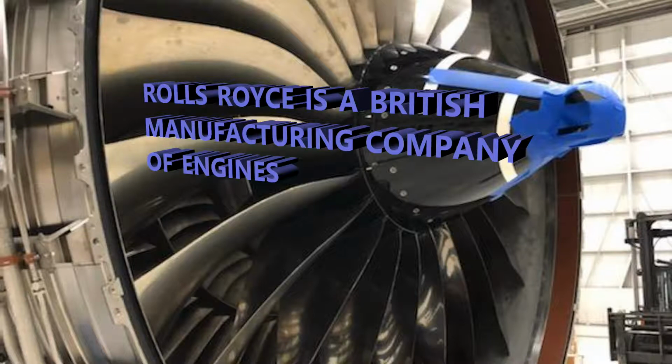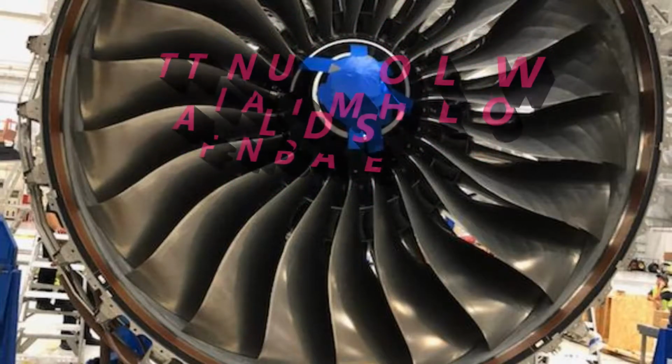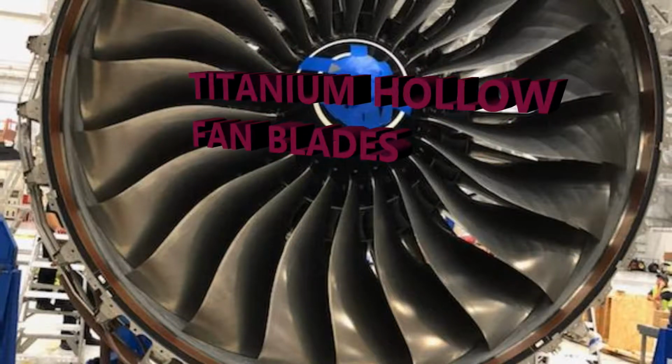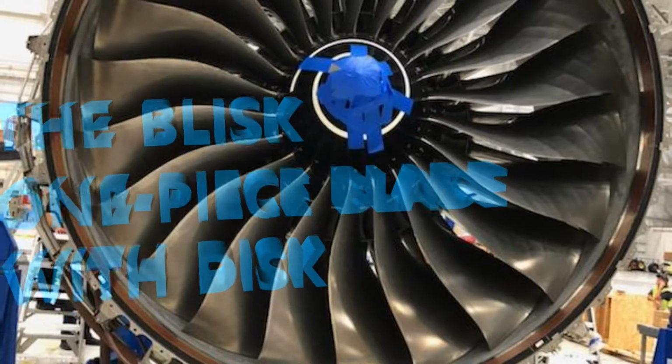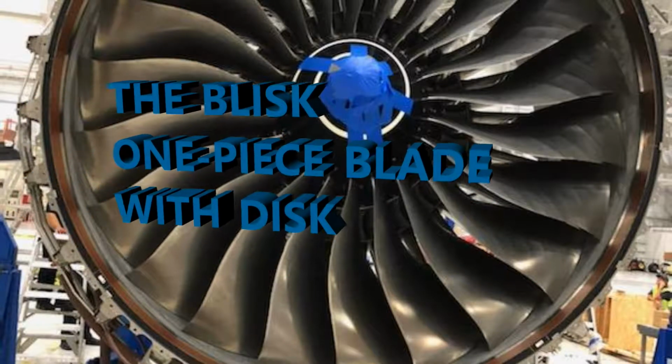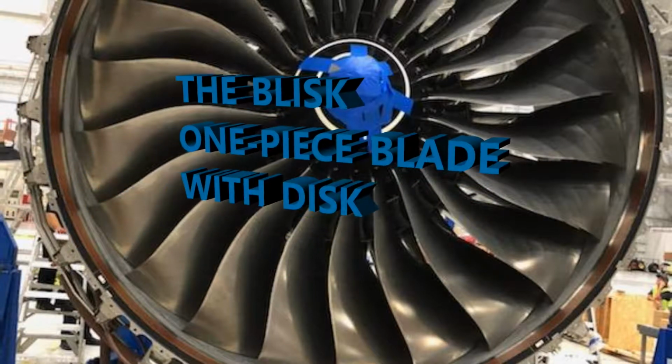The materials themselves back then were different. Today we have titanium hollow fan blades. Also, there's a little difference with the design, in that we have what are called blisks. So we have a combination of blades with discs, so they're one piece instead of two pieces.